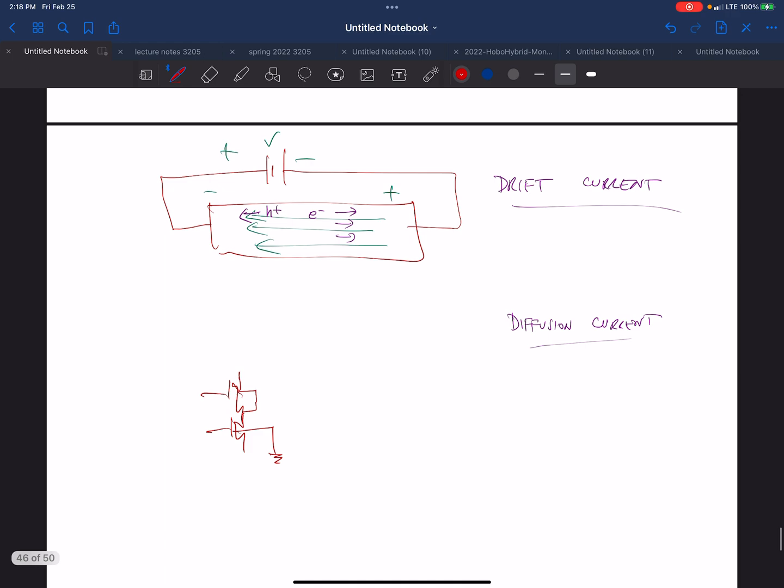So does this make sense to you guys why this is not allowed? Okay, so you can only have the NMOS transistors going to ground. The sources can be in different places. Like, for example, the source of this bottom one is connected to ground, and the source of this one is connected to the drain of that one.